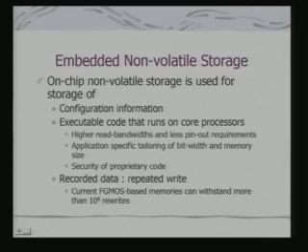Another thing is recorded data. Your voice recorders and your cameras all use flash, which enables repeated writes. Current FGMOS based memories can withstand more than 10 to the power 6 rewrites, and another observation is that once charged, the charge leakage time can be as large as 10 years. So, that is why when you have a speech recorder or a camera, you have these flash cards or flash memory to store the recorded data.